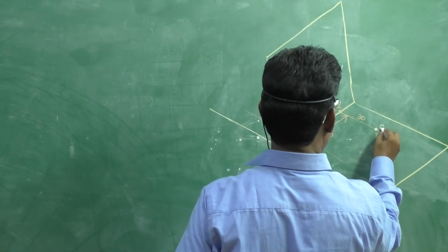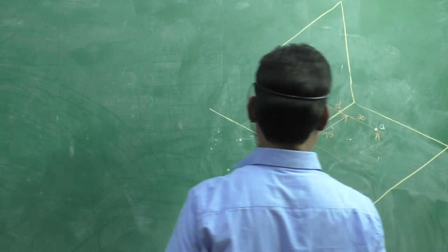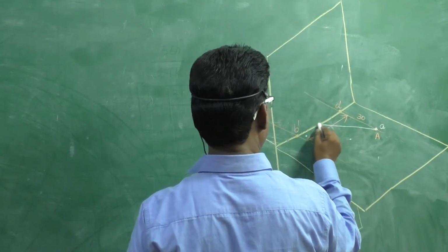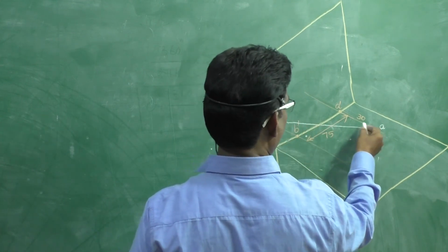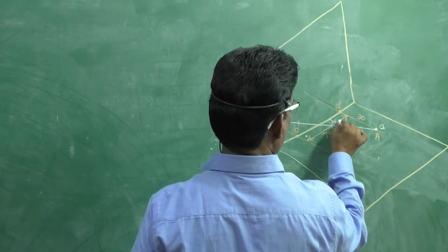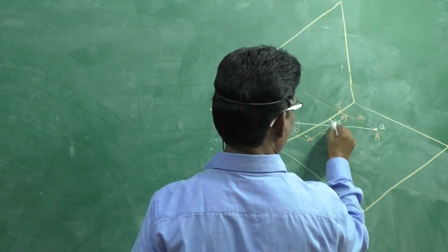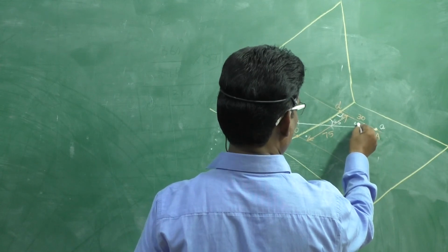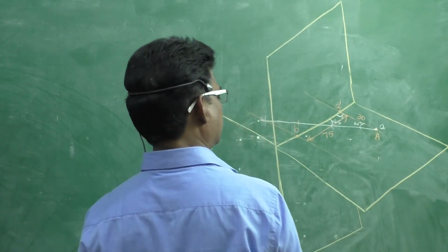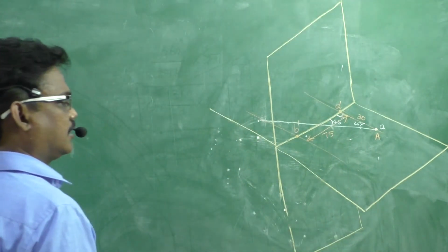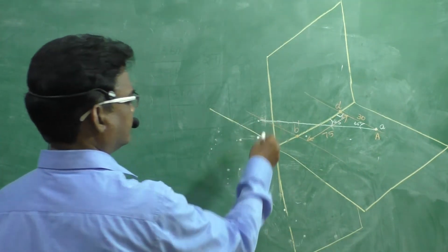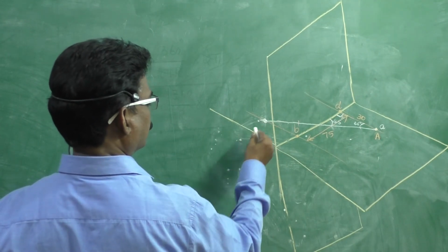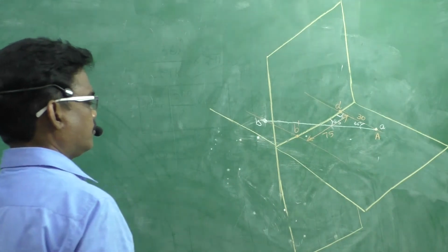This is the top view A, and this is 30 mm. If you draw a line at 45 degrees, here it is 45. This is 90, this is also 45 degrees. Therefore, we can draw the line, and it gives an intercept here, and this is the position of the top view of point B.